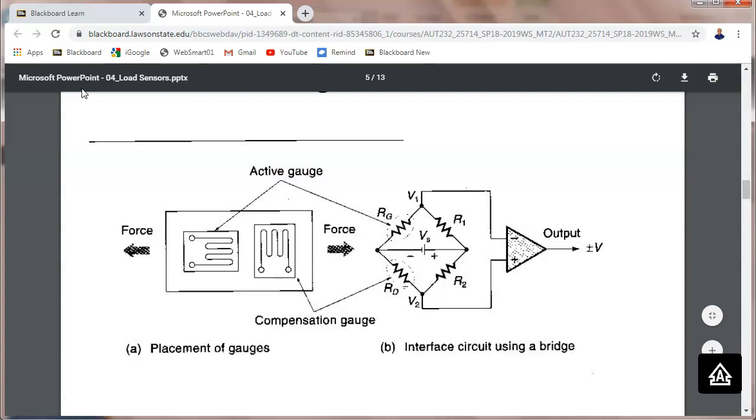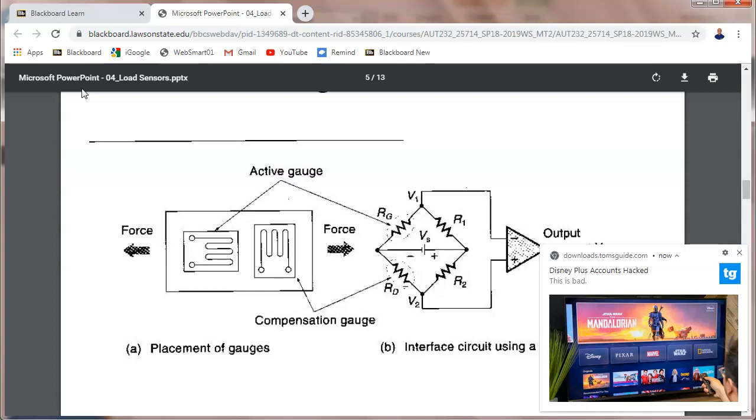So a load cell is a combination of whatever it uses to warp to change its shape with weight. And then it's got the Wheatstone bridge inside of it. You never see this. They've got 4 wires. 2 of them you bring the excitation voltage on. 2 of them your voltage is proportional or extremely accurate. The only thing I do is figure out how to set it to 0.